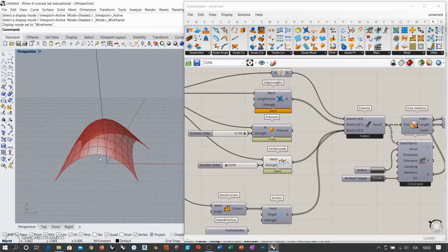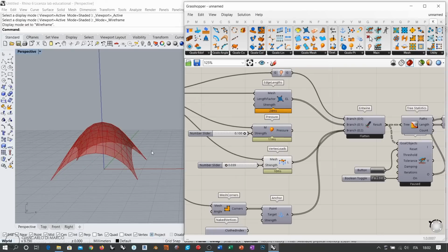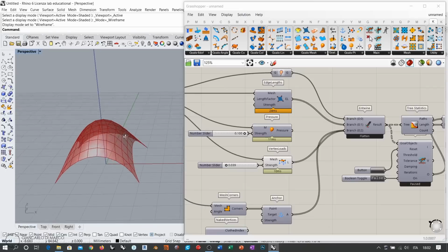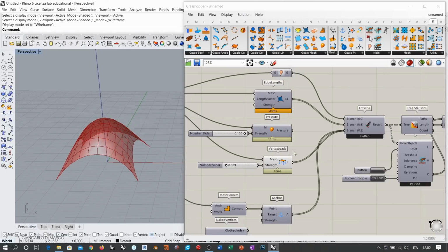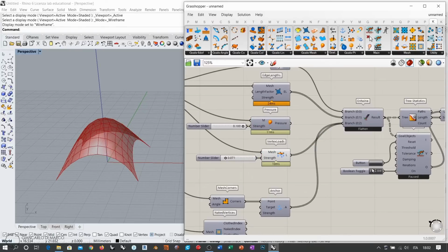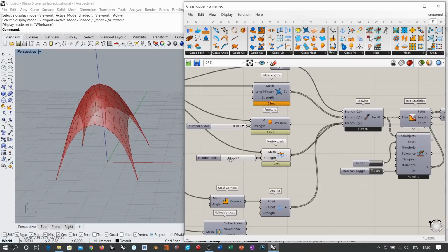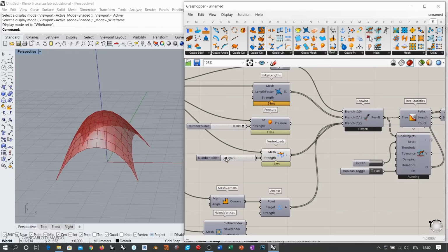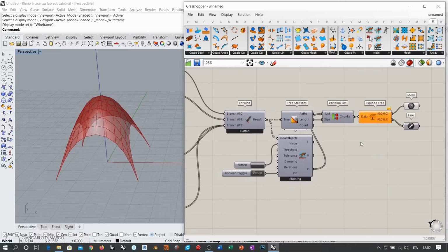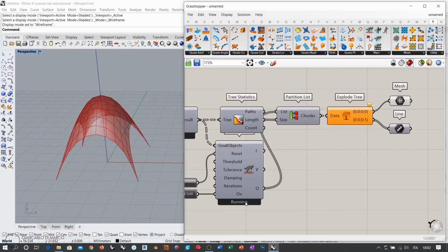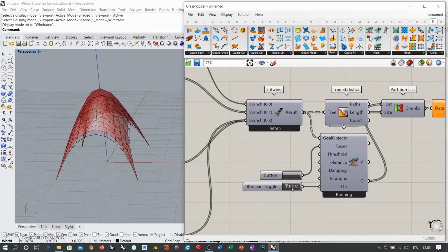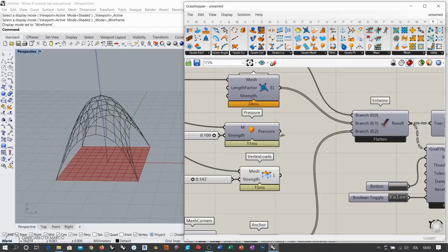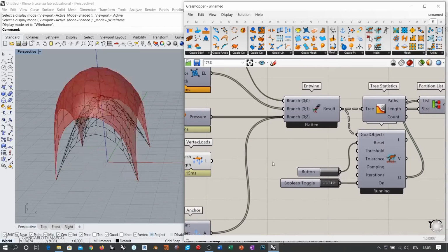So now let's take a look, for example, at what happens when you deform this object with these two different things here. So if I, for example, make this object fall a little more, well, I think this is already enough, like this. Okay, so I wait for this to converge. It should happen anytime soon. Yeah, converged. Take the mesh and bake it in order to have it here in Rhino. Then reset the simulation and substitute the gravity with pressure and run the simulation.